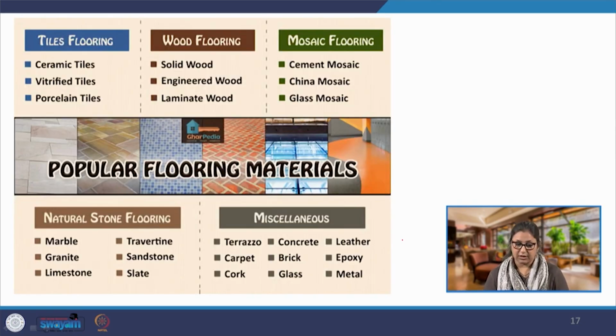If we look at floors, again we are looking at multiple options. We have tiles which are manufactured, and we would be having wood flooring, again there could be natural, seasoned, treated wood. Definitely the floor tiles and wood floor tiles have to be treated well, because they are exposed to a lot of weathering and a lot of different components, unlike walls. So, engineered wood would have higher emissions, and laminated wood would have even higher emissions, because it is now laminated with a synthetic compound. That is further adding emissions to it.